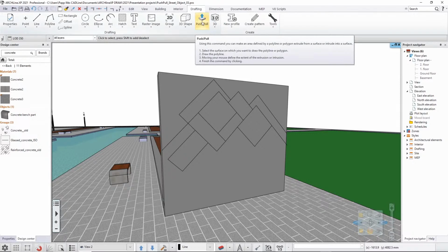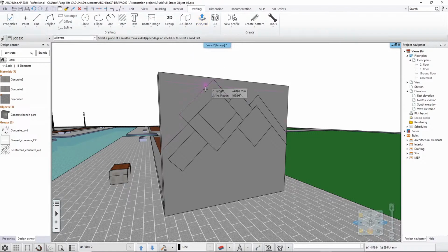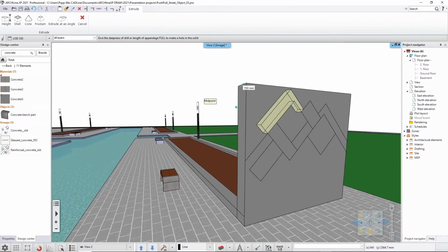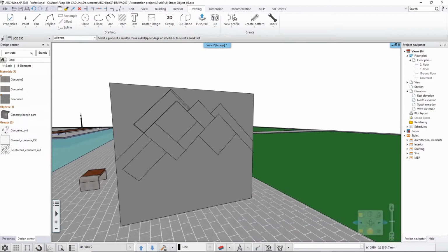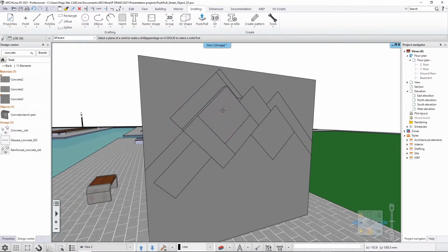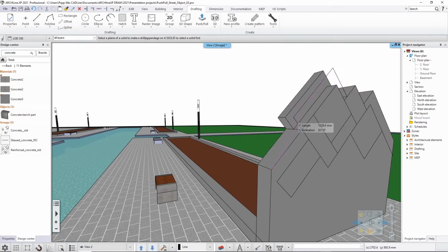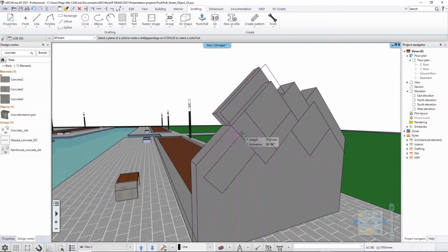So now the first thing that you can do is click on this Pushpull tool and highlight any of those areas that you have created, and then you can just decide the depth of that push pull. If it's, for example, 150 millimeters, which is half of the width of this wall, then it will be just like a partial cut off or a pushed body part. And if you click on the top, for example, and you use it as a completely longer push like this, then it will actually chop that off, but still keeping the previous one in place.